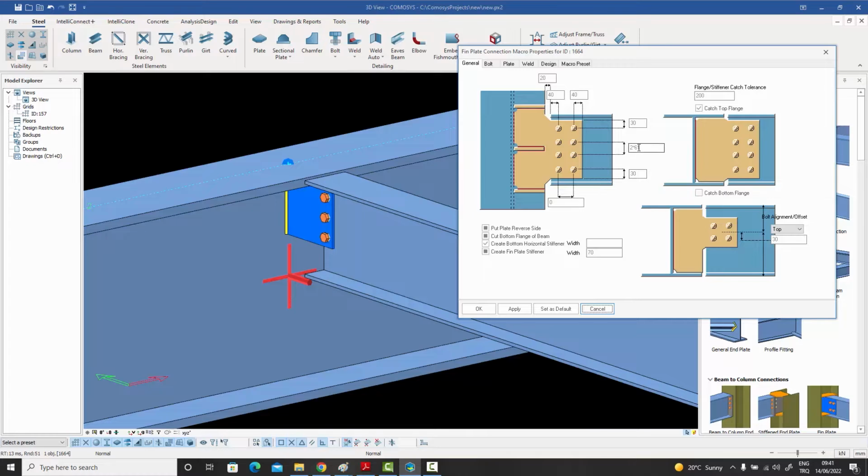So instead of having 3 bolts, I want 4 bolts, let's say, and I want the distance between them to be 50, and this one 0. By the way, there's a general comment regarding entering bolt distances. Always remember to enter both the x and the y directions. When you want to enter something manually, you need to enter both sides of the equation.